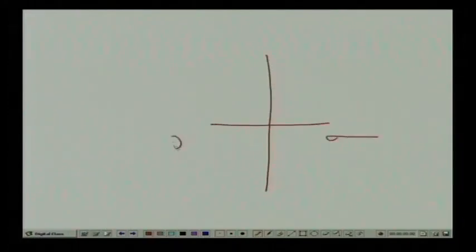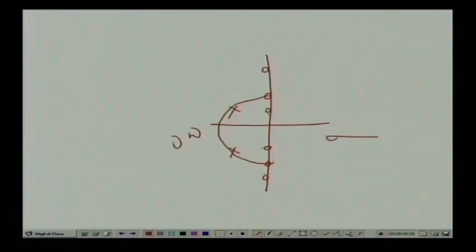this sigma j omega plane, we have complex conjugate poles, and either I can have a 0 here, or here, or here. Now, if it does not cancel, that means there is a real part of the zeros. That is only possible if the coefficient of S in the numerator is not absolutely 0, otherwise there will be no real part. What will happen if the real part remains because the signal subtraction is not complete? The zero will be shifted a little bit to this side, and that will create the problem.